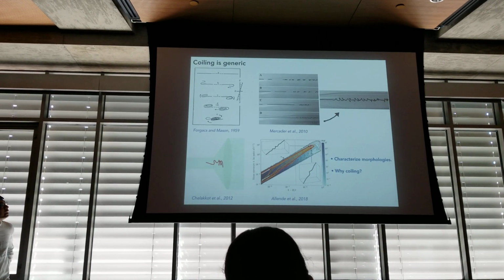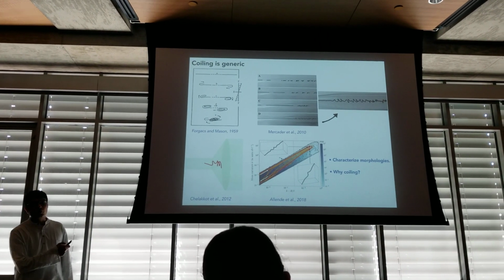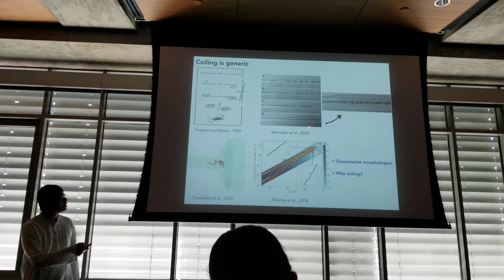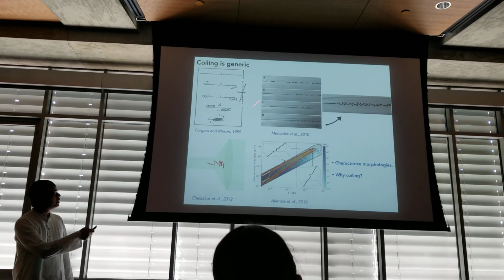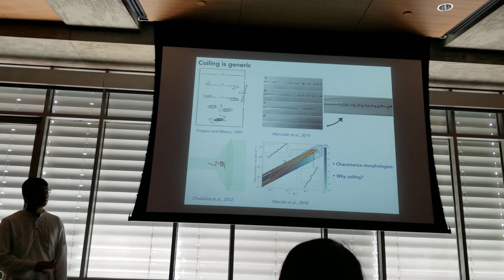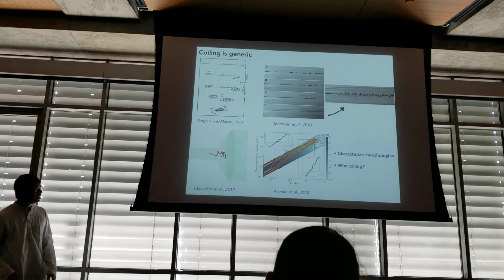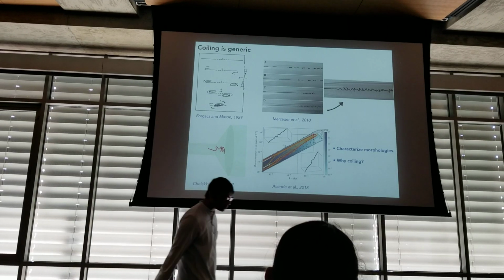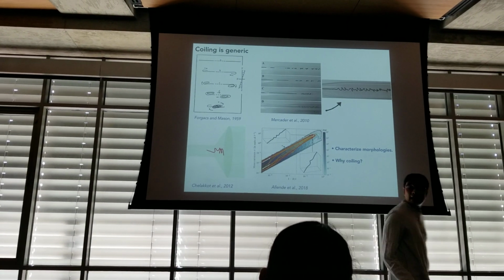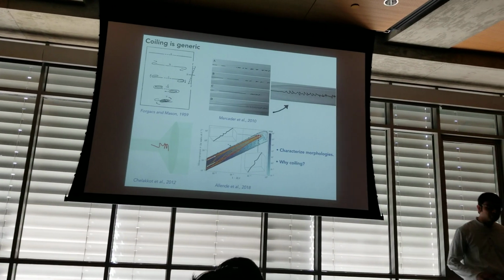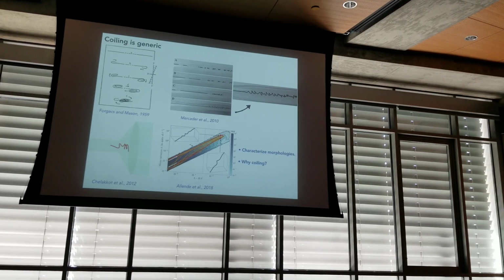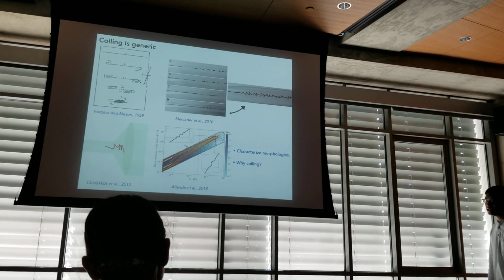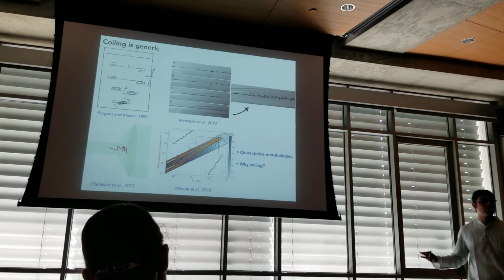We've been observing it in simple shear flow for long wood pulp fibers, seen during manufacturing of wet spun silk fibers in hyperbolic geometries, and also seen in simulations of Brownian polymers in similar geometric setups. More recently, there are some studies looking at transport of polymers in three-dimensional turbulence, and there also you see this helicoidal structure emerging. So it's extremely robust, seen across various length scales and different flows, but there is no mechanistic understanding of why coiling is happening. And that's the question that I want to answer.